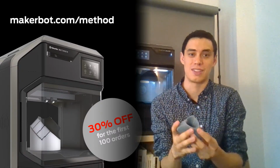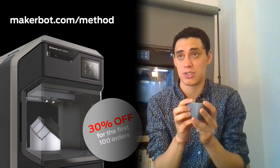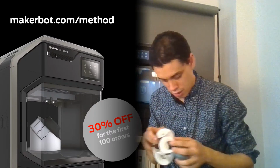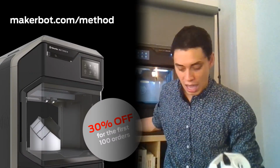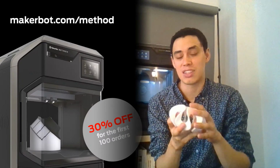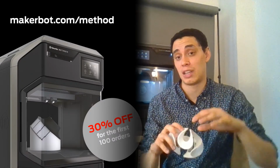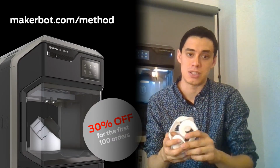And as the processing power became bigger, you had more triangles and smoother surfaces. Simplifying a mesh essentially means reducing the amount of triangles and subdivisions, and that will make your files lighter. But at the same time, sometimes you can see that in the printed files if you simplify them too much. I don't have a good example for that, but sometimes the actual triangles of the STL mesh will start showing up on your printed file. So you have to be careful with that. But reduced mesh is a good way of doing that. If you still have the original curves, you can actually regenerate that model and make it a little bit simpler.